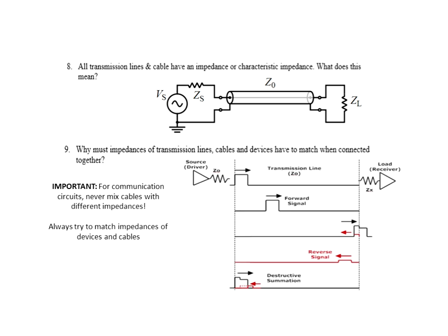All right, another concept about cables that you need to be familiar with. All transmission lines and cables, because it behaves like a circuit, in this case a low-pass filter, will have a rated impedance. And that rated impedance of the cable is very, very important. So, cables that are connecting two devices. Here's a device here, a transmitter, here's the receiver, and here's the transmission line. When the AC gets into the cable, it sees an impedance. When it enters that low-pass filter, there's an input and an output impedance when it leaves it.